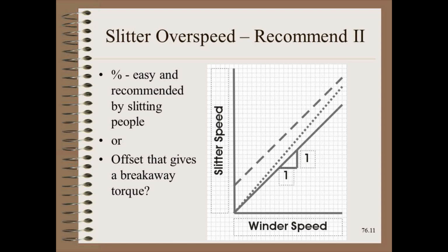So, given experience, how do we actually program drives in the real world? The previous tables and things like it indicate a simple percent may be desirable, and that is how geared drives work. However, in the real world, that may not work well for independent motor drives. The reason is that we need a breakaway torque at low speeds. Thus, an offset may be better, and in fact is often what is done with AC scalar motors.